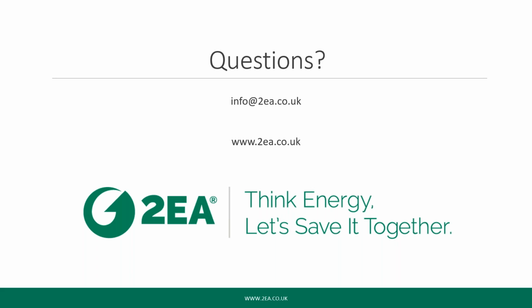There's normally a large maintenance bill on a CHP towards the end of 10 years operation, typically 10 years. So if you take out a maintenance contract for 10 years and are clever about it, that normally gets wrapped in. So you pay a tiny little bit extra for every hour that you run, but you're covered at the end of year 10. So you get a nice fully refurbished CHP.